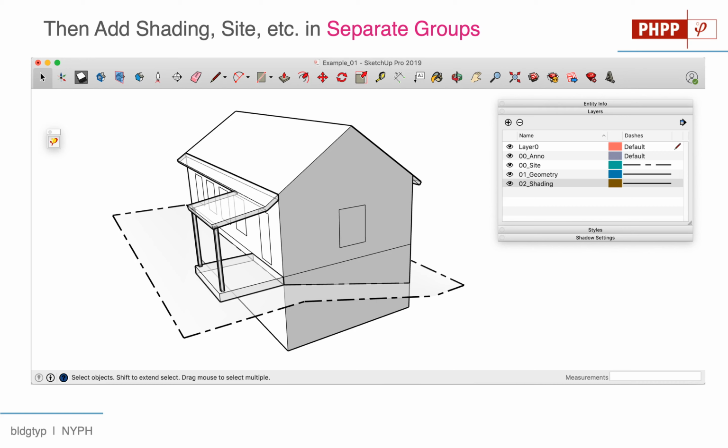So we're in many cases going to kind of split up the geometry of the building in a way that doesn't realistically map onto the real world. Your roof might actually just be one big surface, but for our purposes, we're going to split it into the heat loss component. And then, as you see in the image here, there's a little extra bit that's going to be related to shading, but that eave, that overhang there, would not be part of the heat loss surface of the building. And so we're going to kind of split that off and put it in its own little bucket.